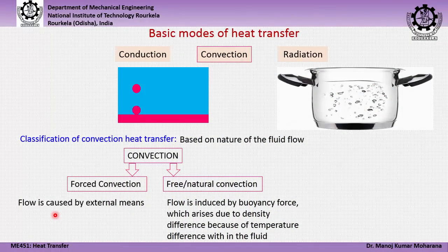whereas forced convection is nothing but the heat transfer to the fluid because of movement of the flow caused by some external power input. So, to make this forced convection, we can use some external power input for movement of the fluid. For example, let us say here in the same container where now this water is still, we will consider one small fan or stirrer, and this shaft of the stirrer we can connect to a small motor, and when you give power to the motor, the shaft of this stirrer will rotate.